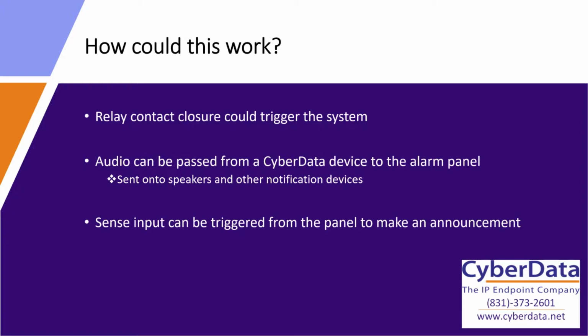And when you're talking about fire alarm panels, they generally have two different sets of outputs and inputs on there. They've got the regular relays on there, which, just like a CyberData relay, are normally open or normally closed. And depending on an action from that fire panel, they can either close the normally open relays or open the normally closed relays. And then you can wire that into a CyberData device, and that device can take an action based on that relay closing, which gives you that automatic capability.